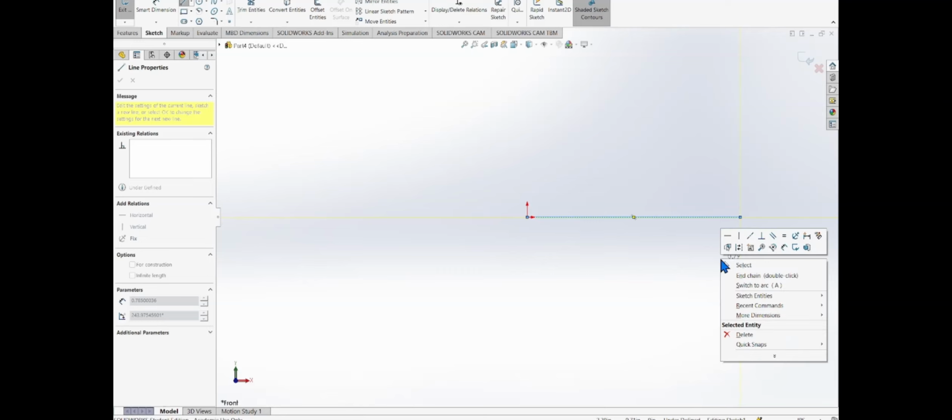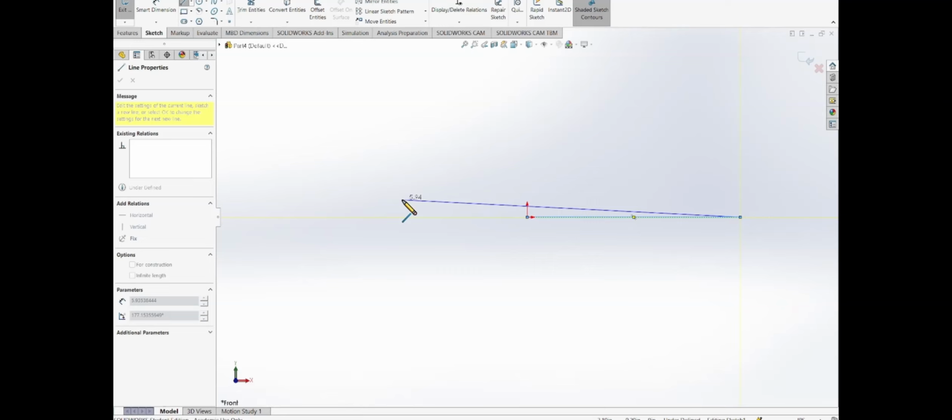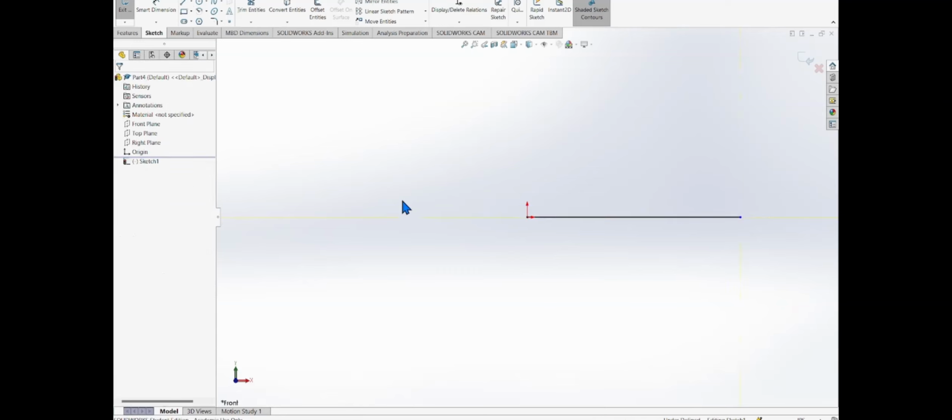That's it. I'm going to right click it, actually check it first, or escape. Escape is the key on your top left corner, the ESC, to cancel everything else or finish the command. That's what there is right now. There's no dimensions on this one, just a guideline. It's what makes the rotation of the line itself, or the rotation of the part.